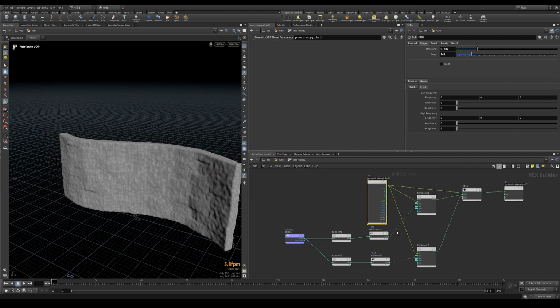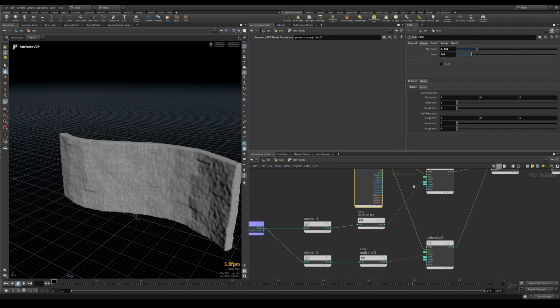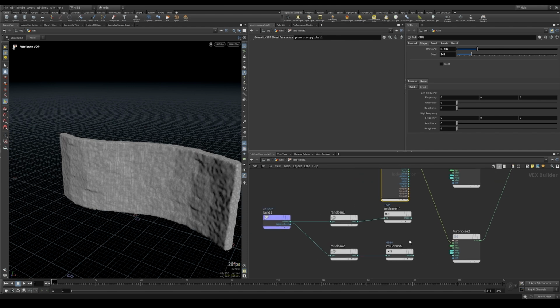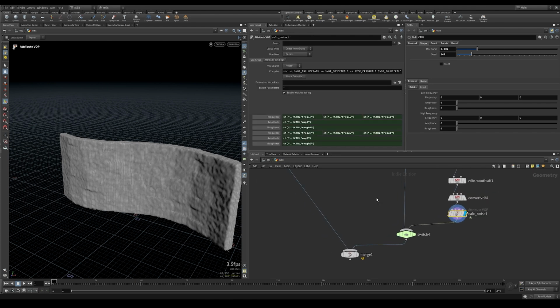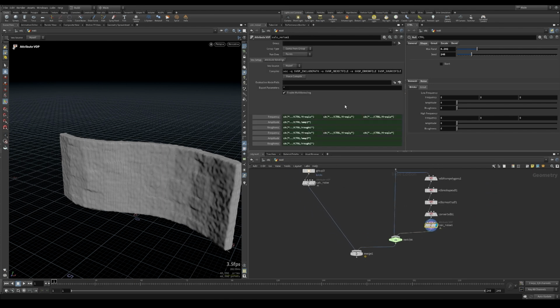And inside the VOP we can delete this offset part because we don't have that call seed anymore, and of course we don't want any randomization over this mesh because this is a single mesh. So all we need to do now is to link this new parameter to this one. And as you can see here, we have all the parameter with the 1 and the 2. And by duplicating it, now we have the 3 and the 4.